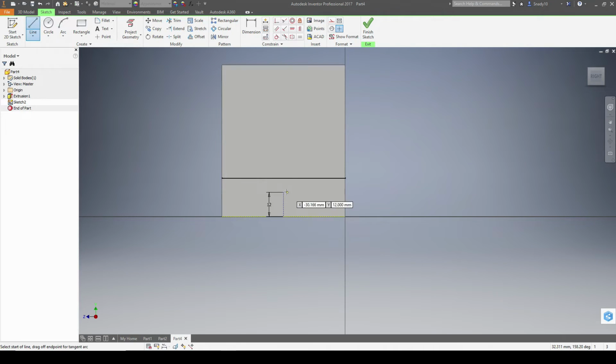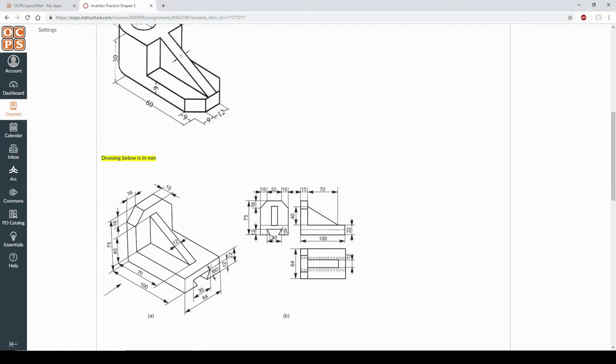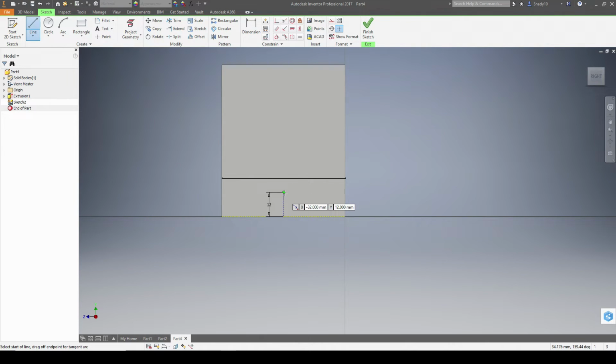And then I can reselect my lines. And I'm going to make a line that is 30 in length. And if the center point is here, I need to make it 15 this way. Don't know why I went to an angle. I'm going to undo that. Needs to go 15 this way. And then it needs to go 15 in this direction. Then what we're going to do is we're going to make a line. And I'm actually going to delete these dimensions so that they're not in the way. Or actually, I'll bring them out here so they're kind of up and out of the way.